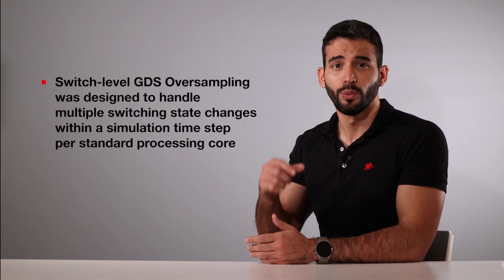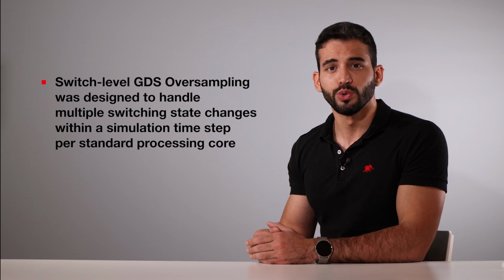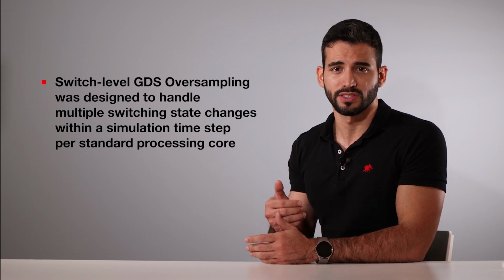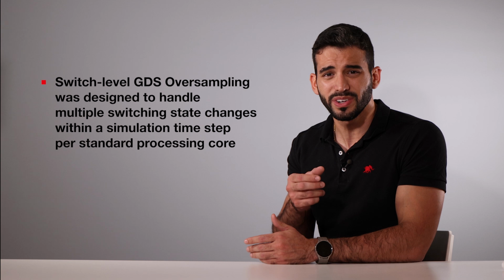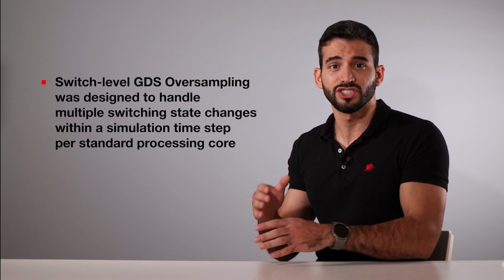While the global GDS oversampling is available for all converter models and often meets the needs, there are scenarios where multiple switching states change within a single simulation time step in the same standard processing core. To address this, we've introduced the switch-level GDS oversampling, which tackles the inherent limitation of the global method by capturing multiple switching state changes in a single simulation step per standard processing core.